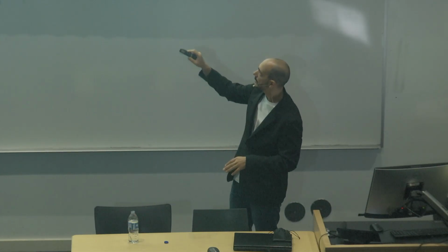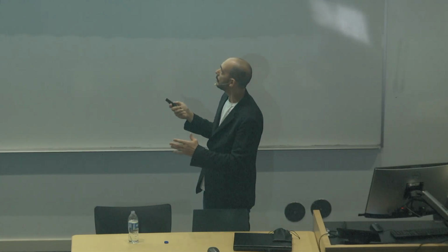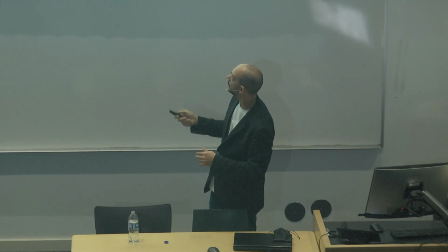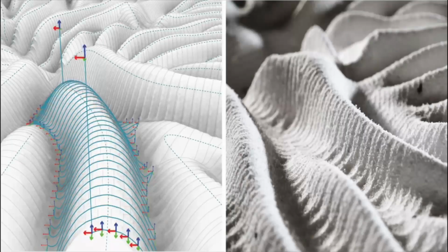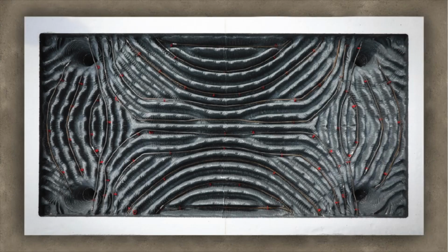And in this case, they were producing some strange results. So we realized that the best effect was when the milling path was perpendicular to the reaction diffusion pattern. So in some of the tests that we did, we were actually using also the reaction diffusion pattern as information of how the milling path was actually working. So you see that here it is just jumping left and right, following the reaction diffusion pattern in order to create a pattern that was low res to save time, but at the same time was creating an interesting effect according to this specific design.